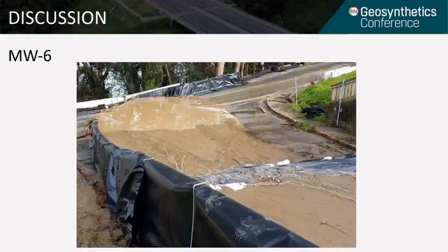While basin MW6 was on a slope greater than 10%, placed on asphalt, and contained empty barrier walls, it didn't experience any stability issues throughout the study period. And this was likely because of its more stable semicircular configuration. It didn't utilize any of the 90-degree corner wall pieces. In general, stress tends to concentrate over sharp changes in geometry. And it was also observed that for some of the other basins where barrier walls had come out of place or rotated, it was a corner wall that was the weak point.